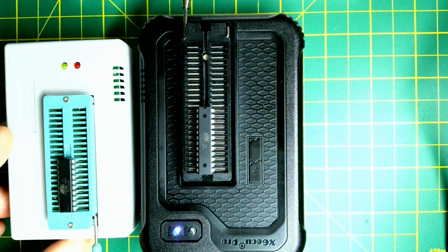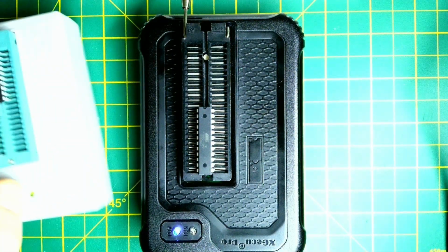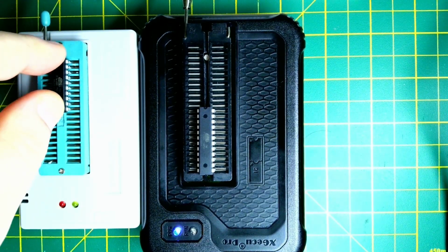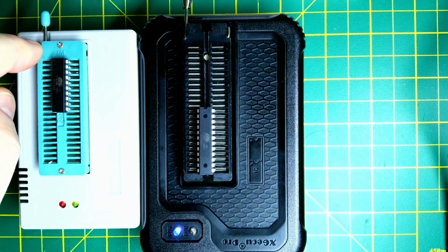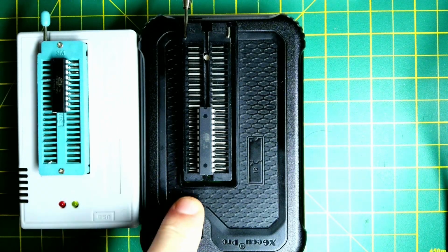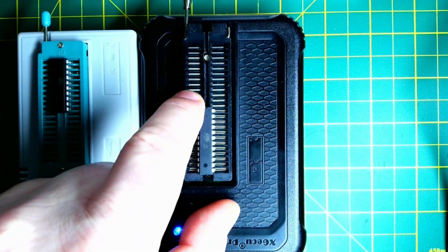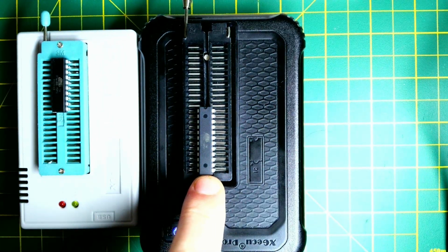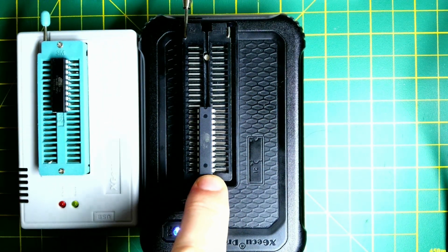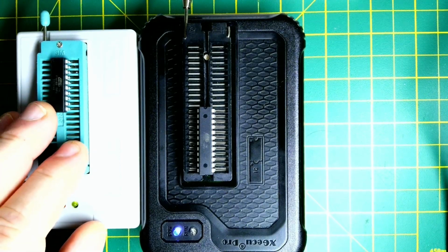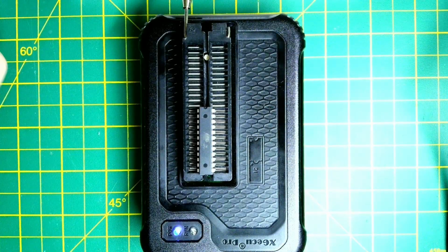So this is the TL866. One of the main differences to notice is that when you're using this one, you put the chip with the pin 1 at the top here, whereas with these ones, pin 1 generally goes halfway up here, so generally you want the bottom of the chip flush here. That's just something to be aware of. It does also have an on-off switch as well, should you want to, and does a much wider variety of modern